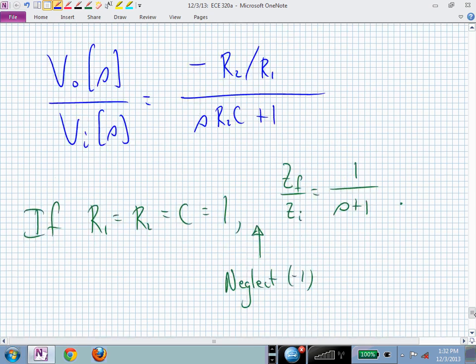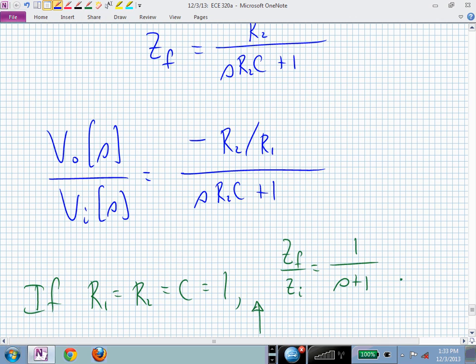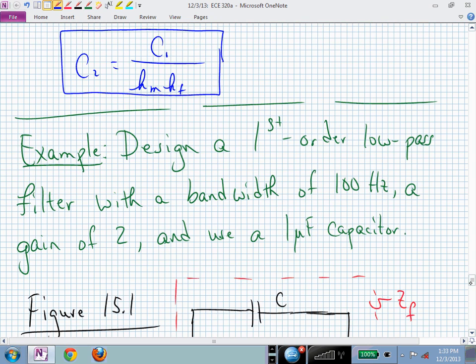Let's first figure out, because the denominator, the pole is going to be influenced by this R sub 2 C time constant. If I can pick that, then R sub 2 might be fixed, but I still have flexibility in R1 to adjust the numerator. So I probably want to go ahead and fix C and R sub 2. C I wanted to fix based on using a 1 microfarad capacitor. The C is fixed. On the exam, you could say, oh, C is equal to 1 microfarad, and I'd give you 1 point out of 25 for that, right? You wouldn't lose points. That's correct, isn't it? So your final capacitor C is 1 microfarad. You could do that without even doing any design, right? You at least got that out of this lecture, I hope.